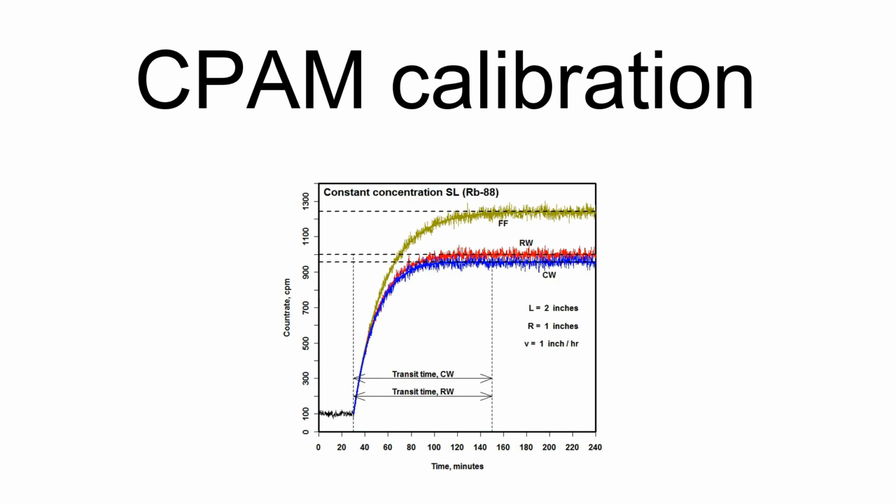The calibration of a CPAM usually includes: 1. Choosing a quantitative method. 2. Estimating the parameters needed to implement that method, notably the detection efficiency for specified nuclides, as well as the sampling line loss and collection efficiency factors. 3. Estimating, under specified conditions, the background response of the instrument, which is needed for calculating the detection sensitivity. This sensitivity is often called the minimum detectable concentration or MDC, assuming that a concentration is the quantity estimated by